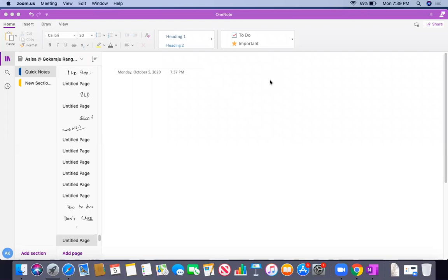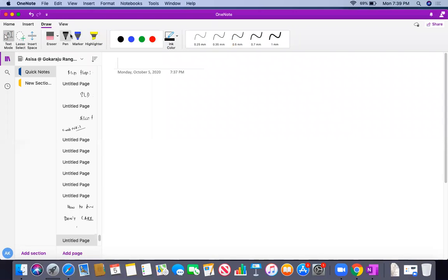So good evening, students. In the previous class, we discussed the JK flip-flop, and we also discussed the disadvantage of the JK flip-flop, which is nothing else but the toggling of the outputs when J and K are 1. When J and K are 1, we get a toggling output. Toggling output means the previous output just toggles and gives the opposite output.